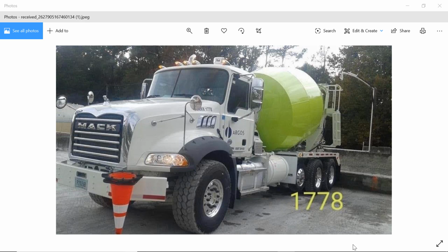Coarse aggregate free moisture is equal to 3.5%, which is equal to 3.5 divided by 100 plus 1, which is equal to 1.035.